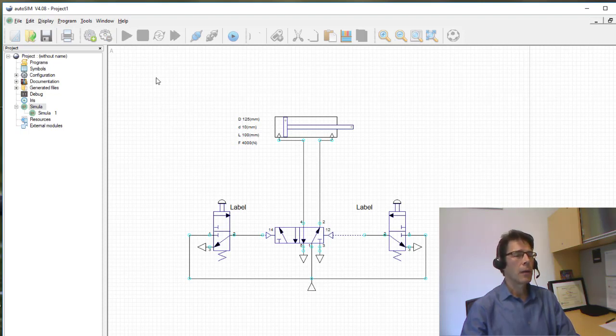Once it's compiled, we go to Program and Connect. Okay, and then this brings up the simulation. Now to run the simulation, we're just going to click Dynamic Display. This thing over here looks like a soccer ball. And now the simulation is running.